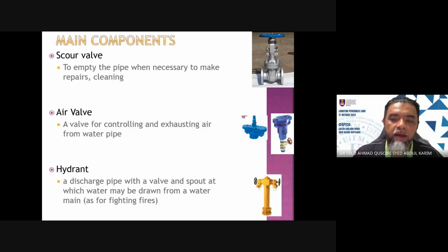So this air valve facilitates controlling and exhausting air from inside the water pipes. So if there is any air inside the pipes, it will gather at this air valve, and once the quantity is enough, it will be ejected through the air valve through pressure.